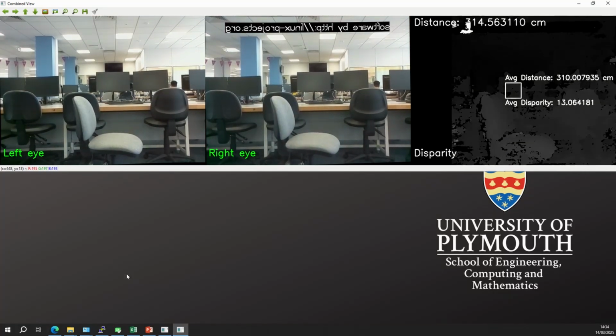So, in conclusion, we were able to first make a successful stereo vision system by using template matching, which took a picture of our desired object, and then we were able to search the environment for this object with matching levels to see if we had confidence levels that exceeded 80%. And then we took multiple pictures of this object and were able to run them all simultaneously to get better readings. And we also converted it to grayscale to stop distortion.